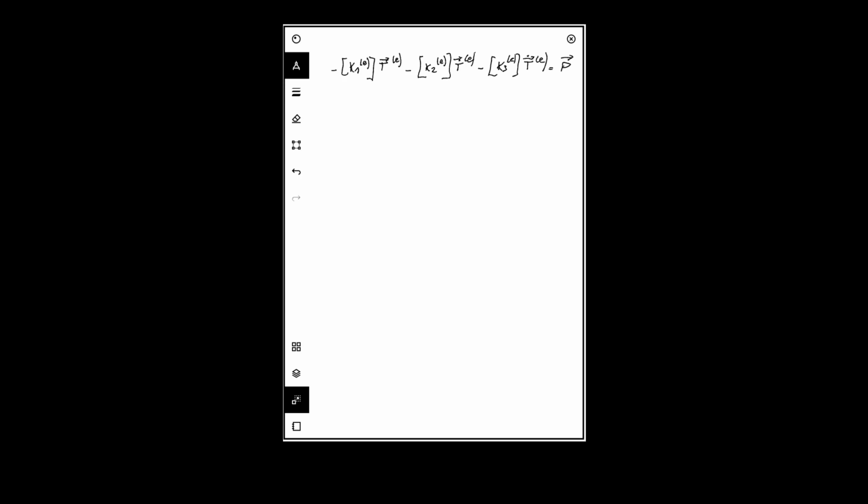But P is composed by P1 minus P2 plus P3, in which P1 is equal to the term we have obtained before, the integral of rho c Ni T dotted dV. P2 is equal to the integral on S2 of Q0 Ni dash 2. P3 is equal to the integral on S3 of h T infinite Ni dash 3.